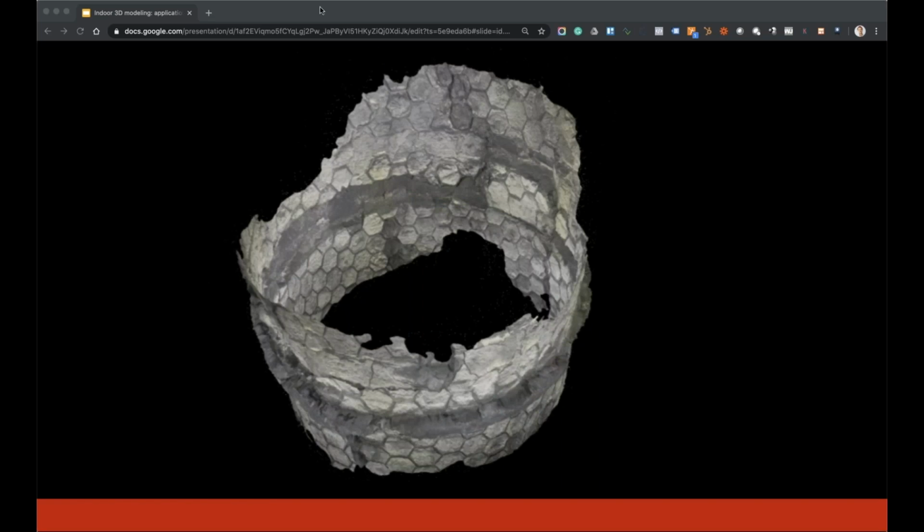And speaking about refractory, this is another example which took place in a refinery, and this is the central pipe of an FCC unit where there was missing refractory. By looking at the feeder stream, it was very difficult to assess if there was anything to be done for repair. And building a 3D model was a very good helper to make the decision whether or not further maintenance was required.